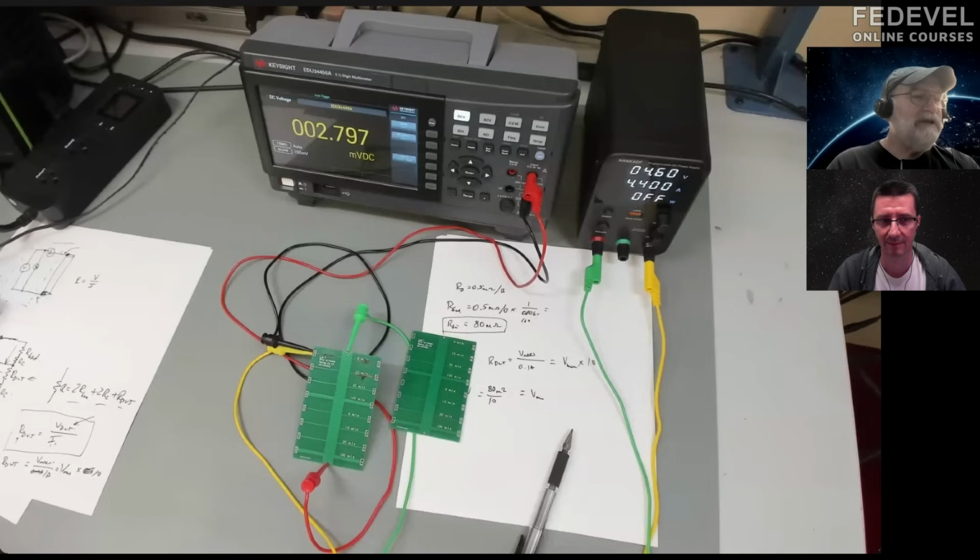I didn't mention it, but the 2-wire, we don't usually call it 2-wire, it's called an ohmmeter. They're traditionally 2-wire. We call it 2-wire to distinguish it from the 4-wire. And 4-wire is another name for the Kelvin method. So it's a method of separating the current paths to a component and the voltage paths that we measure. And it was developed by Lord Kelvin. It was William Thomson in the 1850s.